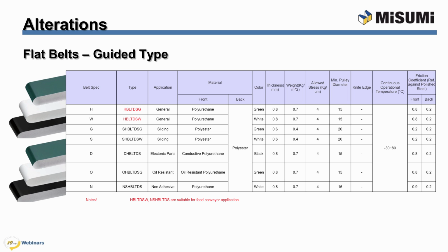Guided flat belts are also available in several options, just like the non-guided belts. The standard belt for general use is either in green or white, sliding purpose, anti-static for electronic parts, oil resistant, and non-adhesive.